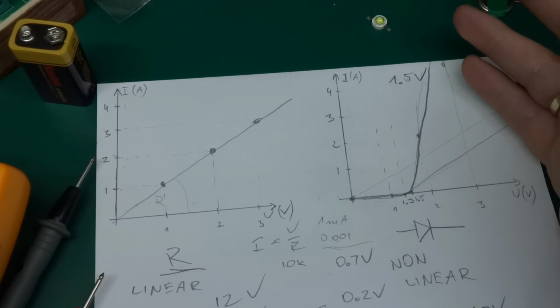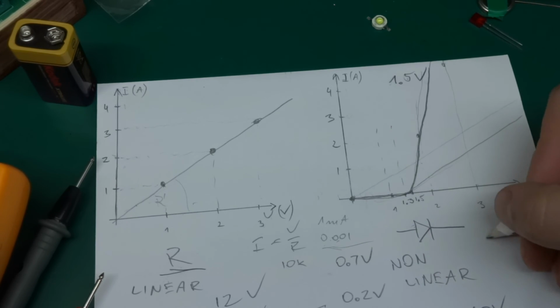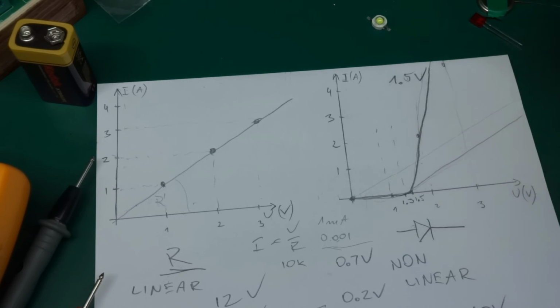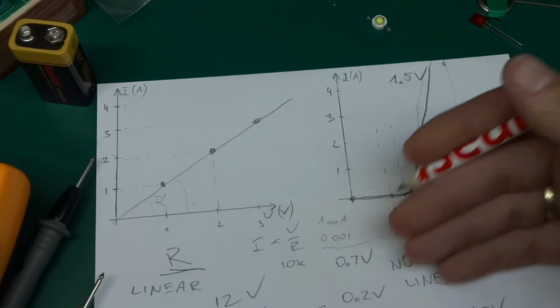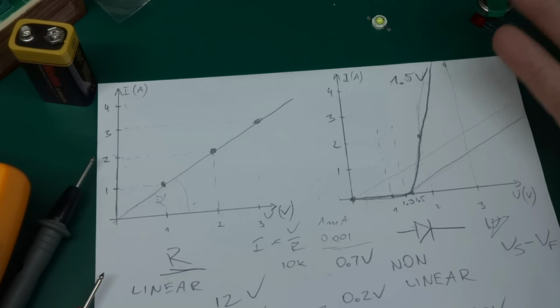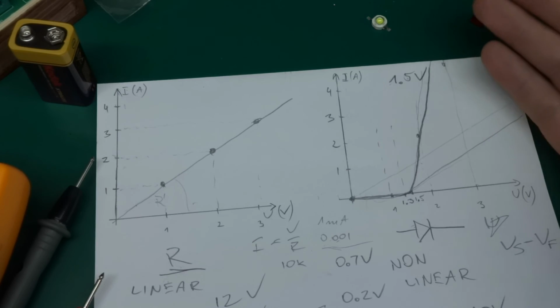Even the high power LEDs, the ones that require 60 volts, they will light up with 5 milliamps easily. They will light up with 1 milliamp very, very dimly. So yeah, this is basically how to do it. Just simply calculate the resistor that you need. That's all there is to it. Quite simple actually, but it's easy to get caught out.